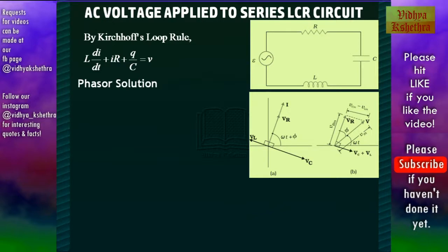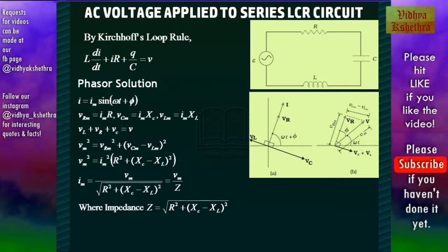We know that in the resistor, V and I are in phase. In the case of capacitance, the current leads the voltage by 90 degrees, and in the case of an inductor, the voltage leads the current by 90 degrees. Now in B, we plot the vector representation. Now i is equal to Im sin(omega t plus phi) is the current in this circuit, where phi is the phase.